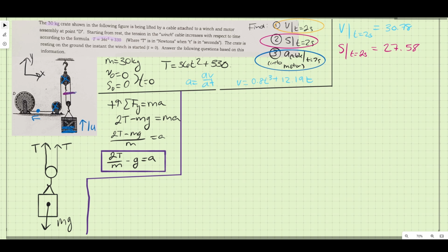And when we lift that crate up, we're going to notice that the 2 cables that are attached to the crate are actively moving the crate. These 2 cables here will each have 1 unit of slack in them when they're picked up. Now we're going to allow the pulleys to turn, no slipping, and we're going to grab onto the cable right here and pull it out this way towards the motor, and we'll discover that we've ended up with a total of 2 units of slack.